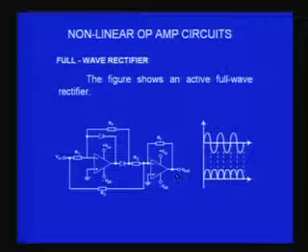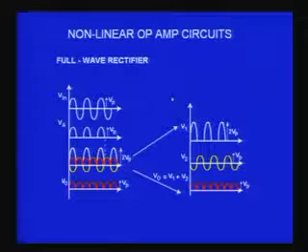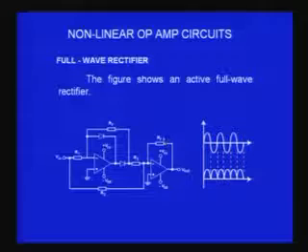So the question arises, how do we get a full wave rectifier when I also have the sinusoidal input here? I will try to explain to you with the signals that I have. Before that, perhaps I should tell you, for example, RF is 2R3, twice R3. The gain factor here for the rectified signal is 2. So R3, for example, can be 10K, RF can be 20K, and this R2 again here is 20K. That means the gain for the input AC signal is only 1, but the gain for the rectified signal is 2. This is the important point that you should remember.